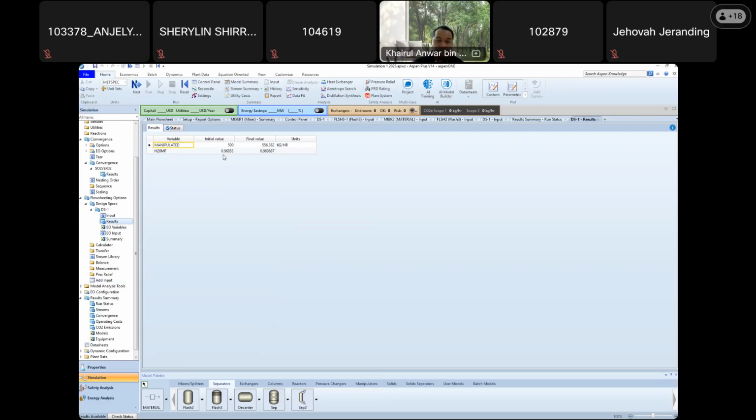In the previous simulation, we went up to 500 kg per hour because we limited the maximum to 500. At 500, the percentage of water is around 96.853, very close, but still below the 97 for the 0.001 tolerance. Then the system adds 56 more kg per hour. We get the 97.